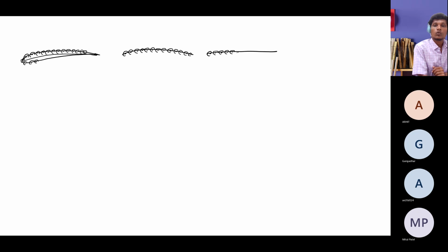Basically, if you say this is more suitable for the symmetric aerofoil, if you try to model this. Now, the condition that we applied is the fluid element should not pass, or any flow vector should not pass through this camber line or the chord line. So, mathematically I'm allowing some fluid velocity U infinity, and this U infinity has a tendency to go up because I'm inducing it with some angle alpha. So U infinity sine alpha has a tendency to move through this chord line.